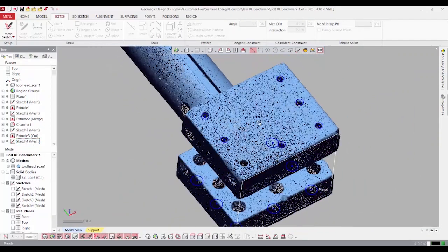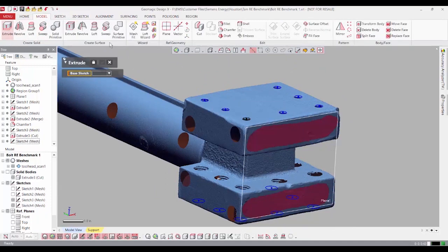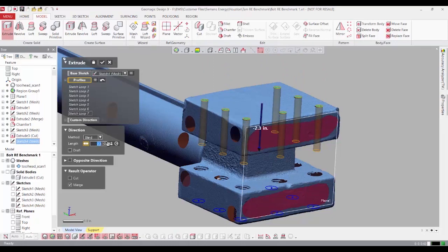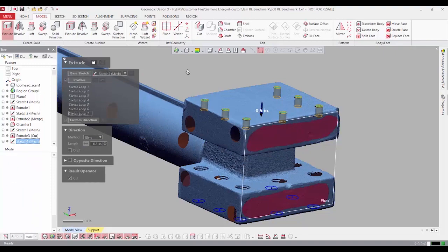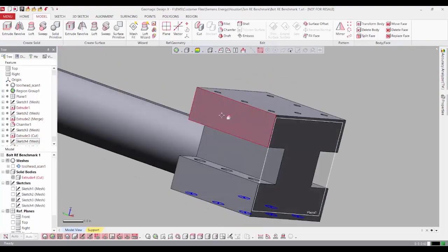Sometimes you might go in and manually measure the depth of those holes. Since I don't know it from this model, I didn't do the actual scanning, I'm just going to flip it and try a 1/2 inch, and that'll work, and we'll hit cut. Again, you can always modify this. Let's bring back our solid body, and there you go.